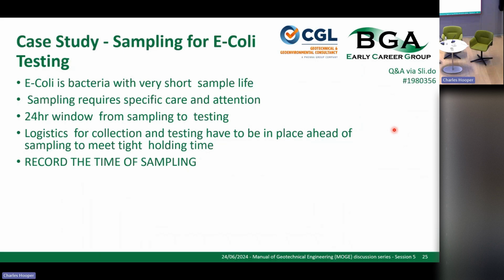Testing for bacteria is challenging. It has a very short sample life. Once you take that sample, it will degrade very quickly, so you have a 24-hour window from the sampling to the testing. And even the sampling process is quite interesting.